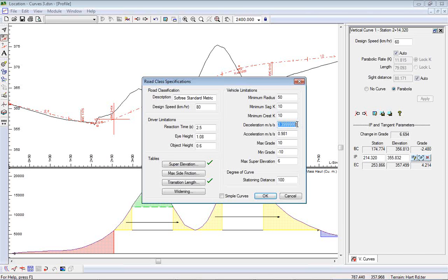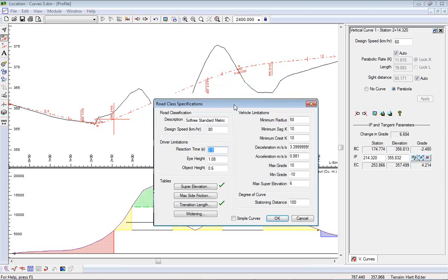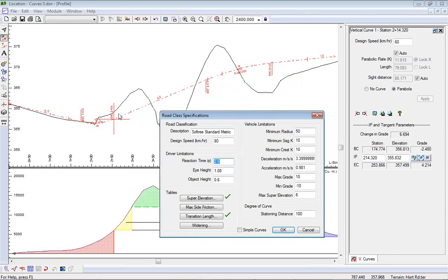So you set the deceleration rate. That's defined by your road, your tires, your conditions, rain, snow, whatever, and a reaction time. That tells you how long it takes to stop, with one little extra factor, and that is the grade. So the steepest grade in a curve is included in that stopping distance, and that's just the most conservative way of defining stopping distance.